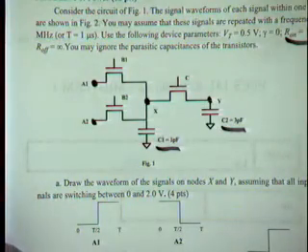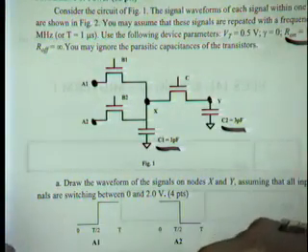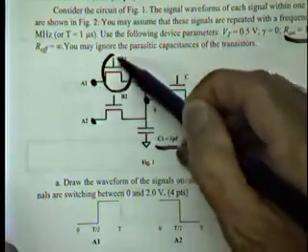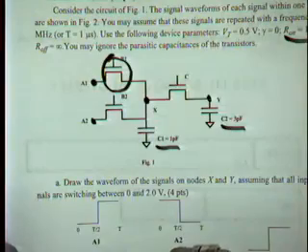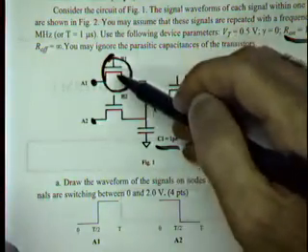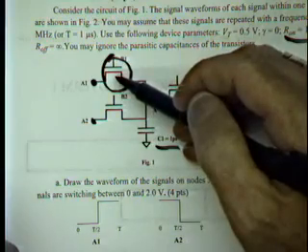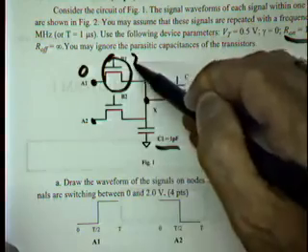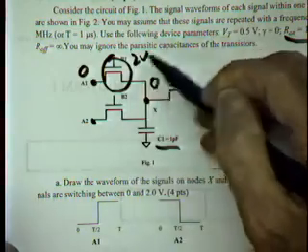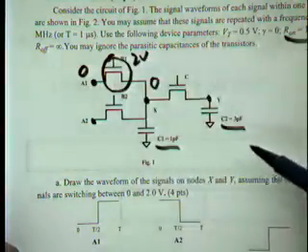Right? So B1 goes on. Node X is initially still at 0. Nothing happens till T4. Now turning B1 on is not going to change anything. This is now equal to 2 volts, we turn on the transistor, but still this is going to be equal to 0.